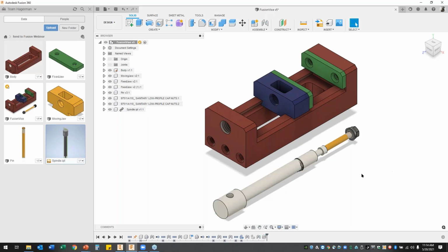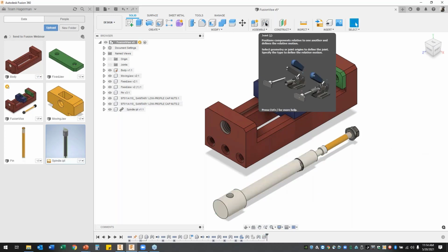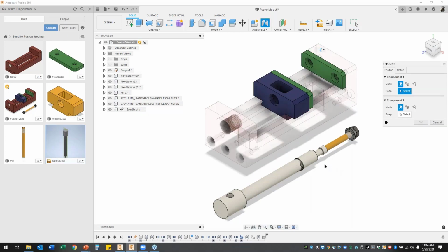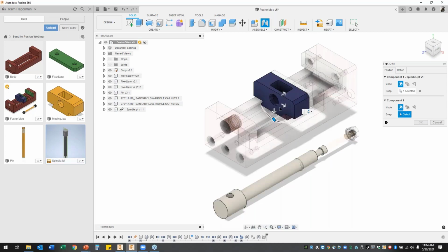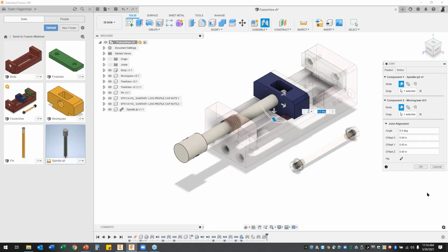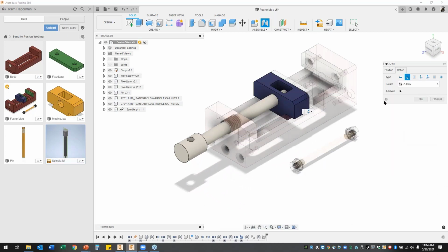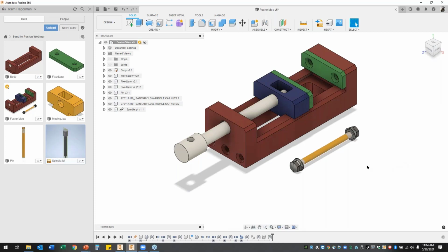And we would normally go ahead and take this and begin to work with our joints to add this into the assembly. So I'm going to select that endpoint and this little circle here. We see a revolute joint, and we can decide, do we want it to be rigid or revolve or slider, and so on and so forth. And we'll go ahead and put that in.